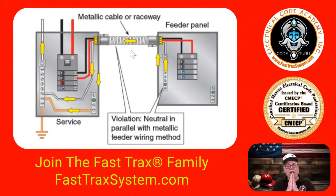But what we wanted to point out with this illustration was that if you just remove the screw, it doesn't remove the issue, because now we still have to make sure that the return path for the fault current is either a raceway or a cable that is allowed to be used as an equipment grounding conductor. And as we said, this is obviously not MC cable. This is obviously not AC cable. The other types are limited by the overcurrent protective device protecting the conductors in the cable, usually to 20 amps or less. So in this scenario, you have a problem.